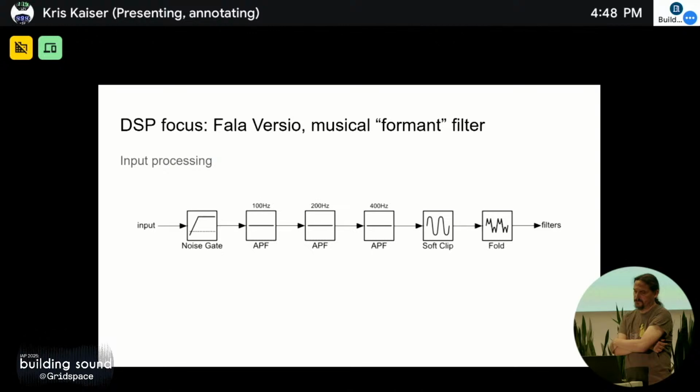In normal subtractive synthesis, waveforms like sawtooths are very common. Sawtooths perform very poorly with a lot of nonlinear effects, because if you try to saturate a sawtooth, you get a sawtooth, so it doesn't actually do anything. So the goal of those all-pass filters is just to distort the shape of it without changing the spectral content. That'll take a square wave and make it into a much slopier looking thing, but it'll sound the same.